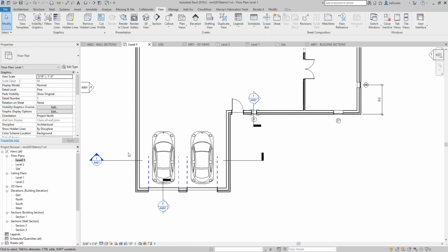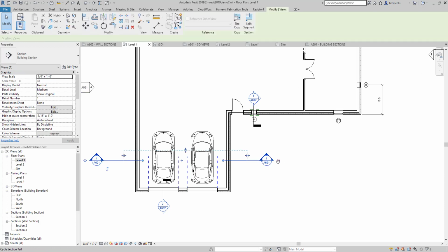Changing the section head tail, I showed you a little bit briefly, but you can actually turn these to change them. Once you see the blue circle with the arrows near the section marker, you can pass your mouse over to see cycle section head and pick on it. You can pick on it over and over again, and you are toggling between 3 different appearances: no line, thick line, and arrow. Repeat for the tail on the other end of the section.